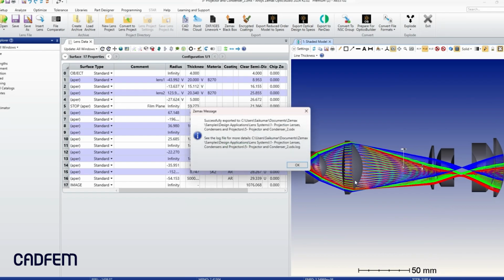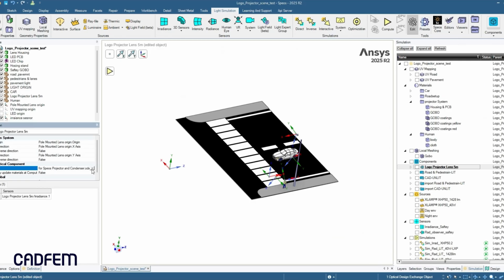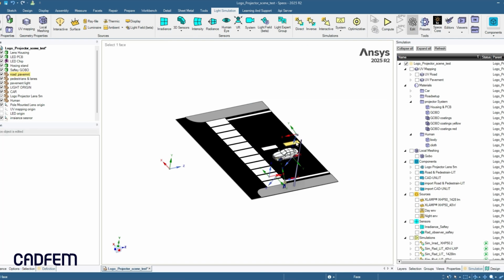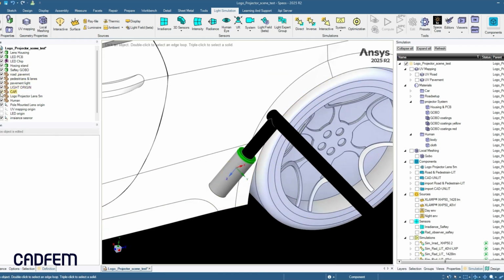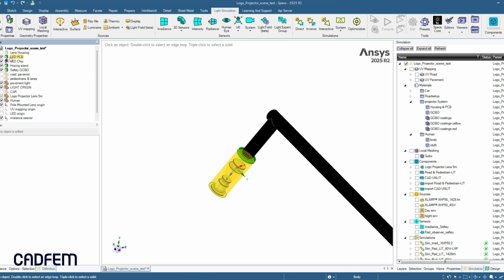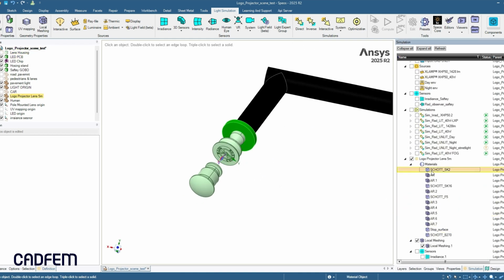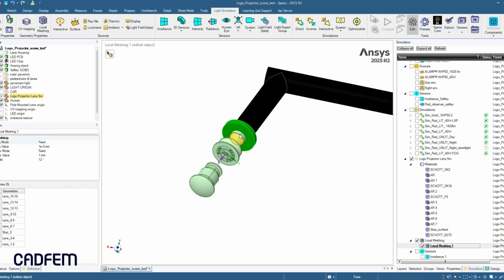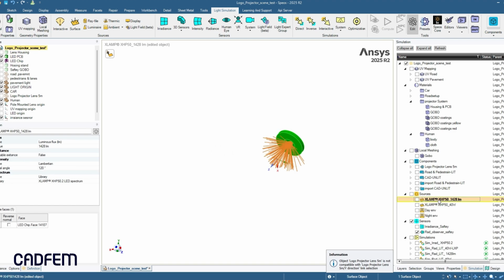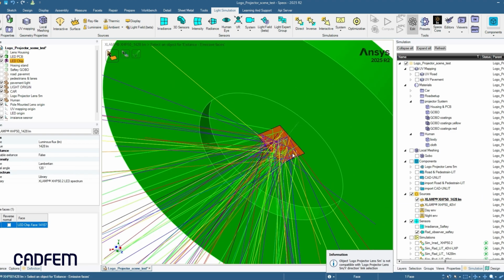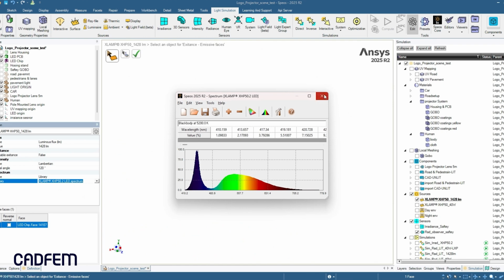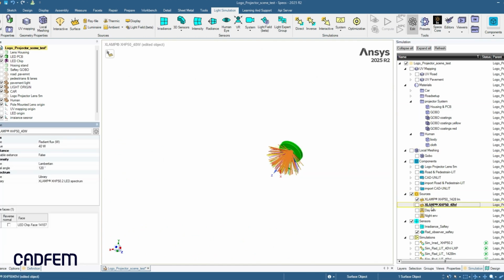Integration is seamless through the optical design exchange. We pull the precision lens array directly from Ansys Zemax OpticStudio, ensuring the light shaping performance matches our mathematical optimization perfectly. By importing the original design file at this stage, we maintain the exact optical prescription. These lenses are assigned specific shot glass properties, providing a high-fidelity foundation for how the light will be steered onto the crosswalk. This seamless data transfer ensures that the mathematical optimization from Zemax is preserved perfectly within our 3D mechanical